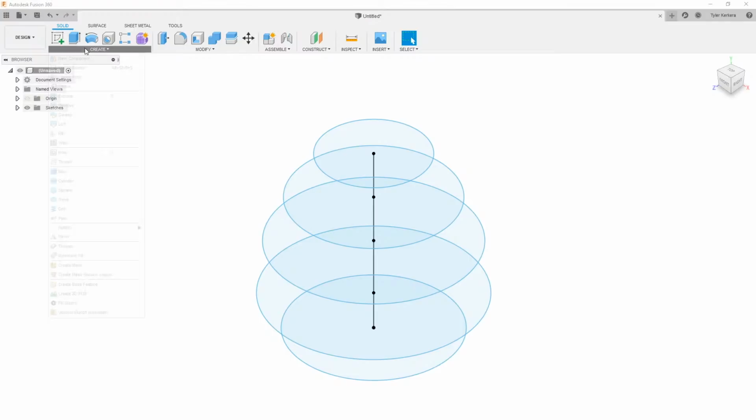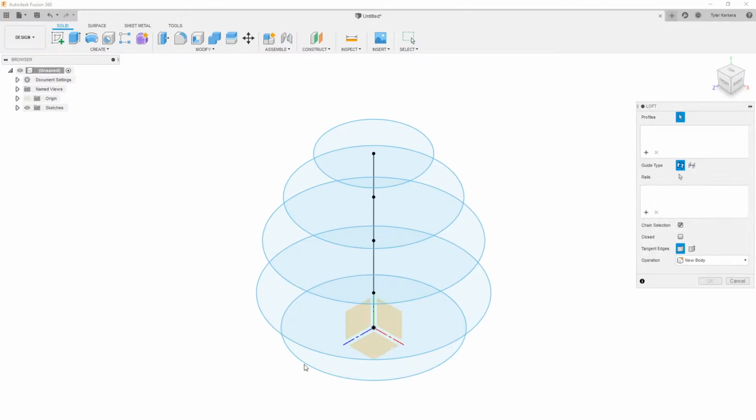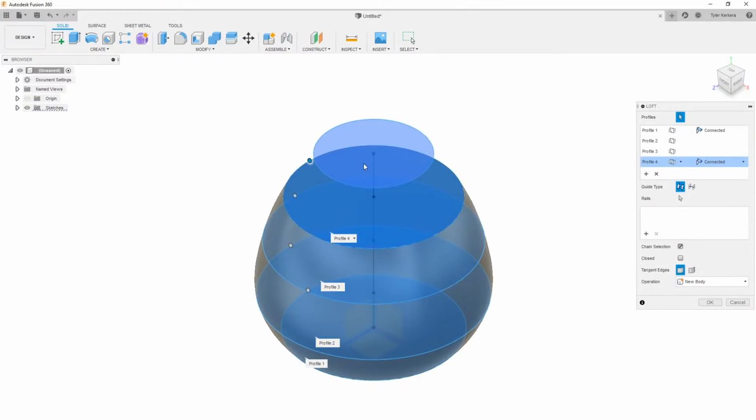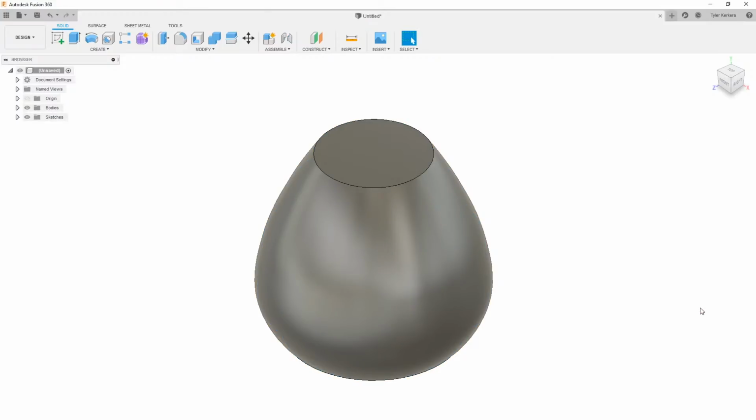So I'm going to say finish sketch. I'm going to go to my lofting tool and then just select all of those profiles that I want to loft into. And in 2 different tools, I've created this really complex shape where this would have been like 5 different construction planes before and 5 different sketches. Now it's just these nice 2 neat options here in the bottom left corner. So just a good example of, again, how this 3D sketching tool works.